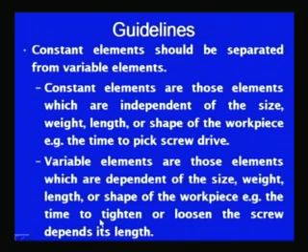For example, the time required to tighten or loosen a screw depends on its length, while in the case of constant elements, switching on, switching off, putting things aside are always constant. So, those elements which take fixed time are segregated as constant elements, and the elements for which time varies with the characteristic of the workpiece are segregated separately as variable elements, so that they can be treated in a different way during the analysis.